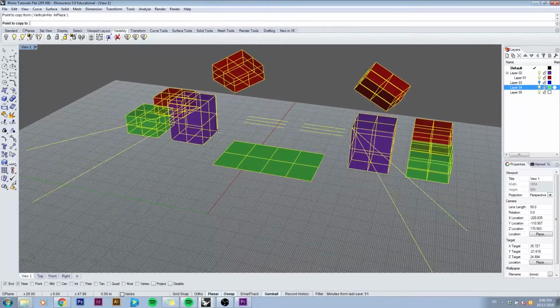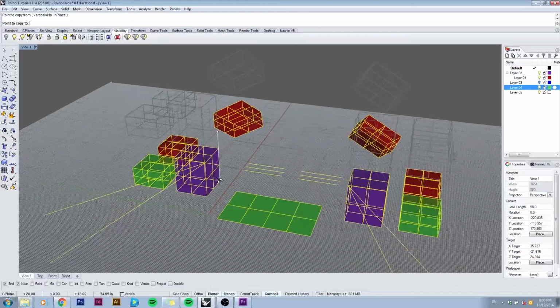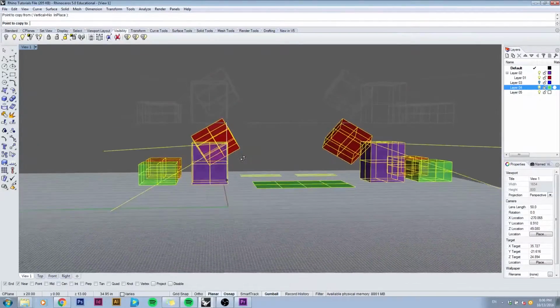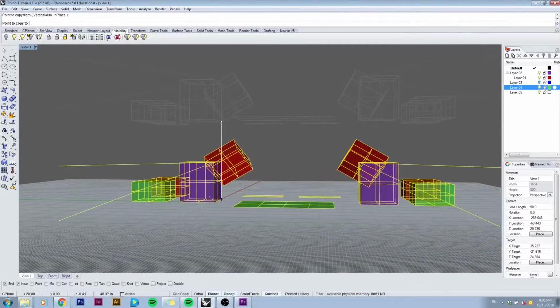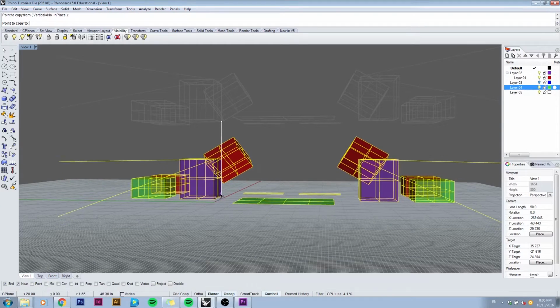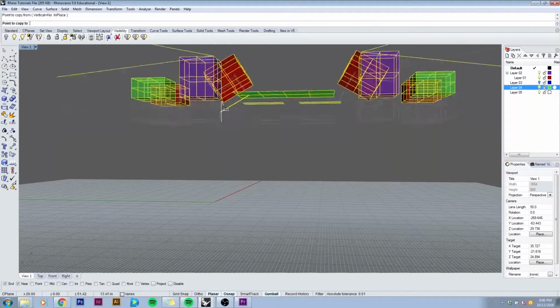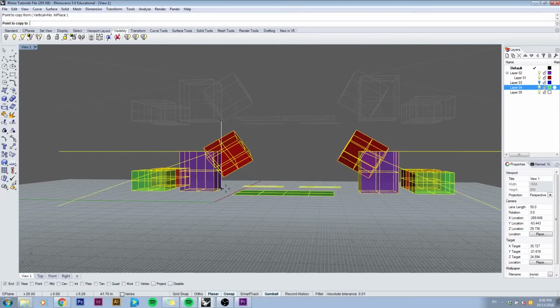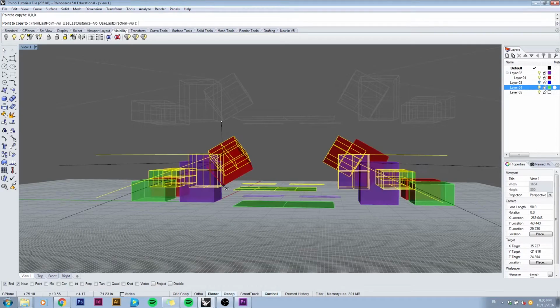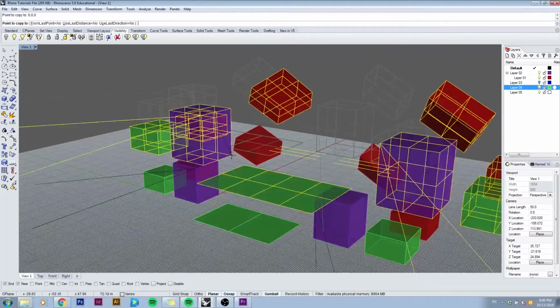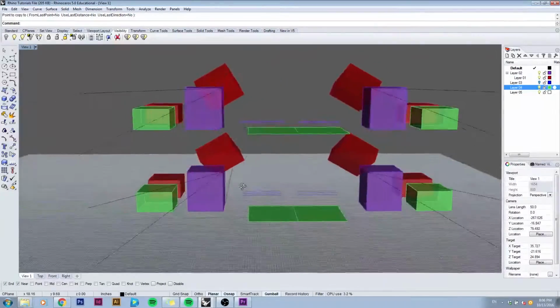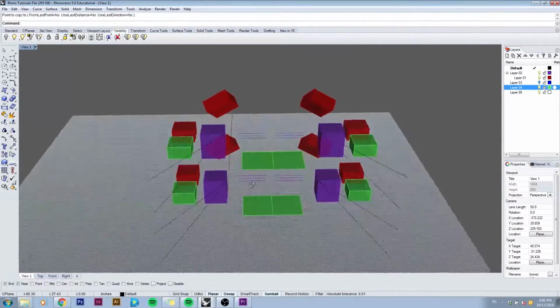I'm going to snap again to this edge, hit Tab, and go downwards. And if I wanted to be at the 0, 0 line, limited to this vertical movement, I can just type in that coordinate while it's in this snap mode. And just type in enter, 0, 0, 0, and enter. And now the model has been copied to its original point.